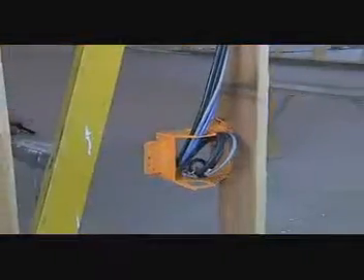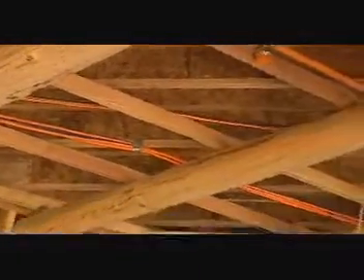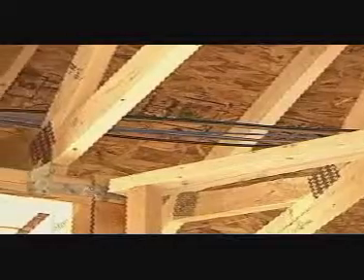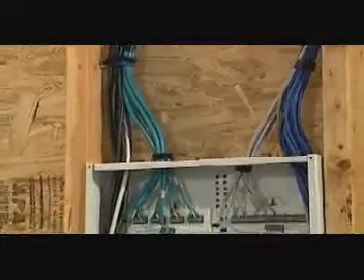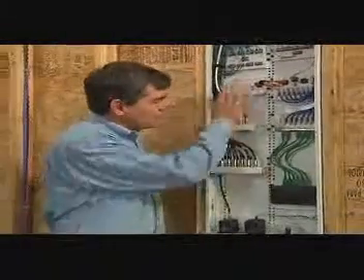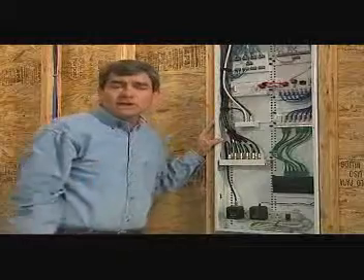course. Structured cabling or structured wiring is a relatively new term used to describe a standardized arrangement or structure of cables and devices installed during home construction. These cables are designed to distribute existing and new telecommunications, data, and audio-video applications throughout the home. The cables originate at a central distribution device, such as this Channel Vision distribution center, and each cable branches from here to outlets or devices throughout the home.